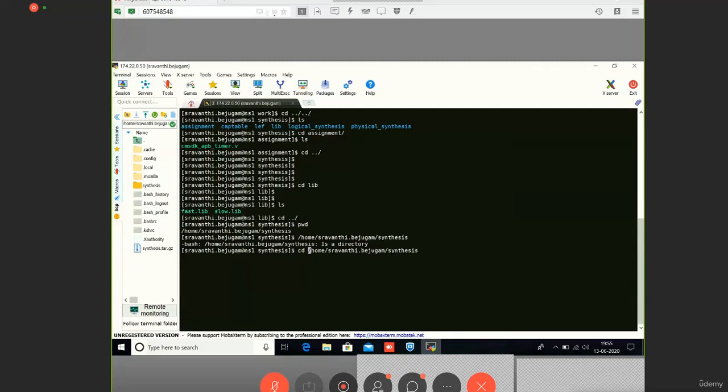Now if you open run.tcl, you can see. Someone asked whether I can invoke Genus anywhere. Yes, the license is set, so you can launch from anywhere. But the directory from which you invoke is the present working directory. When you run the tcl, it will consider paths from that directory. That is the understanding.